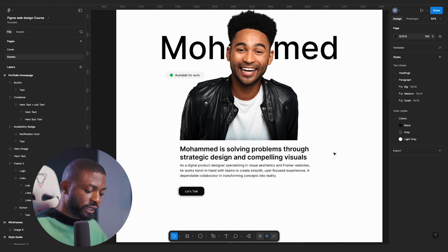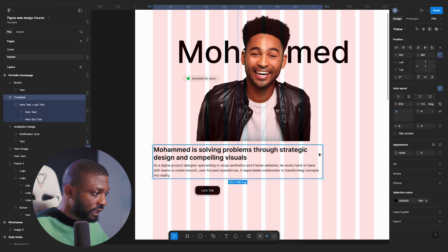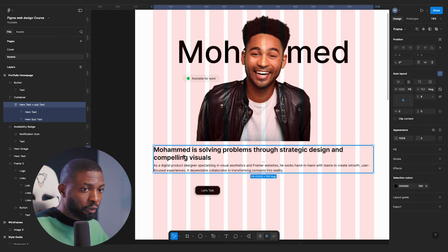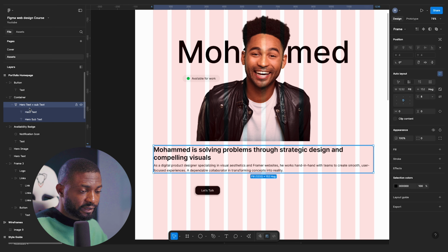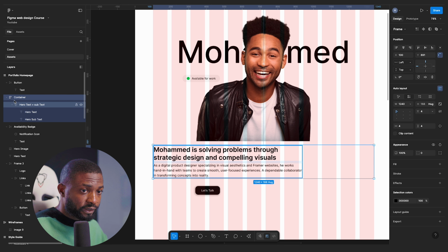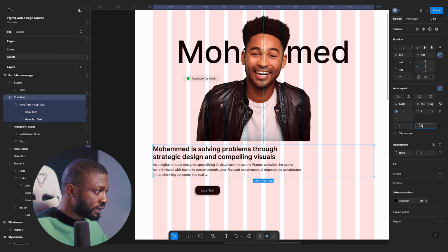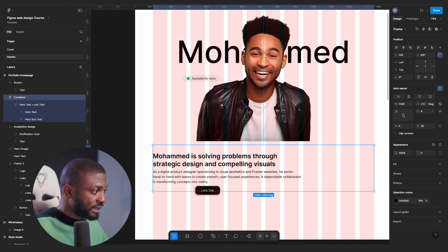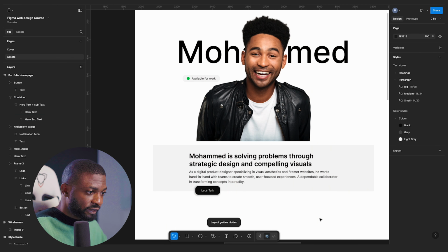Let's just turn on the grid, and I can drag this to this point, and I can drag this to this point as well. Now the container spans around the column grid, but for the text and the subtext, I'm going to reduce that. Once I'm done reducing that, for the container, the spacing left and right should be 0. Top and bottom, let's set it to 40. And then we can set it to be center aligned. I can add a color to this so it will stand out. So let's just add this gray for now, and turn off the grid system to see what we'll have.